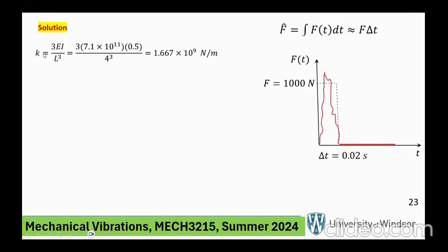Let's plug in the different values that we have for the information provided: the stiffness of the spring, and the natural frequency, square root of K over M. We are assuming that the wing is massless compared to the missile and the missile carriage system. So here is the omega n.